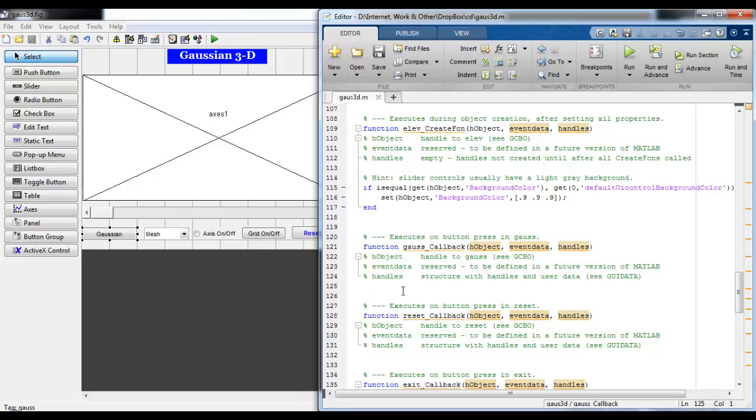So I'm going to tell you a shortcut command to plot a Gaussian graph. You can use the fspecial function from the DSP toolbox, where we created filters. So write H is equal to fspecial. fspecial is the command to create the filters. First we have to define the type of the filter we are creating, Gaussian, and then we define the matrix, or dimension, 100 by 100, and then the variance of this Gaussian graph.